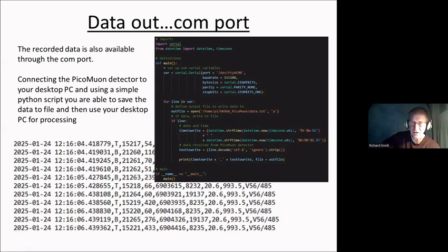The date and time shown here on the bottom half is the date and time that would be gained from the single board computer that was actually recording the data. This is not the date and time that comes from the real-time clock. We suggest the use of a Raspberry Pi 4 or Raspberry Pi 5 because it's something simple that we can all get access to and is easy to program in Python.